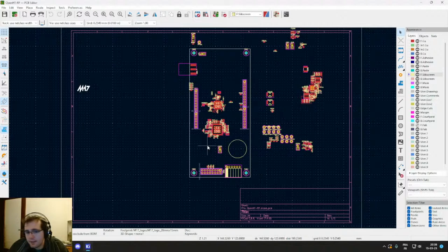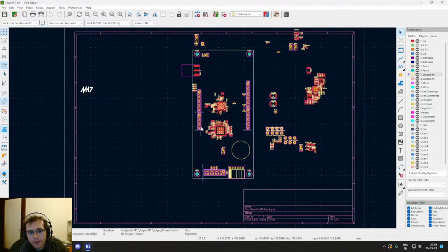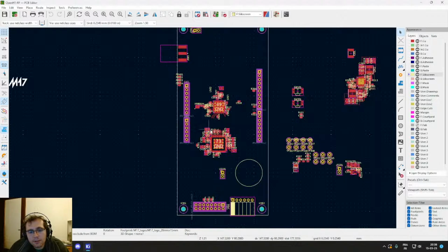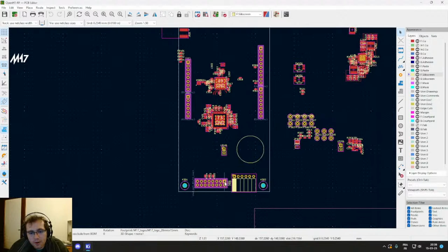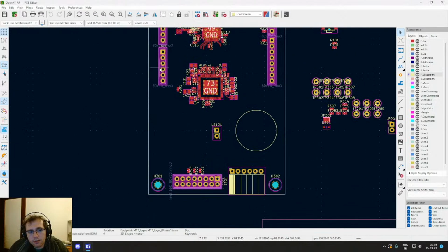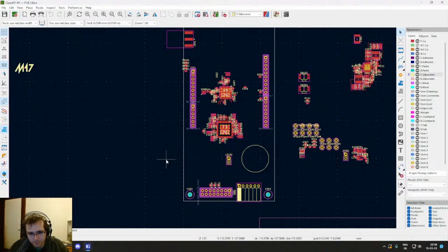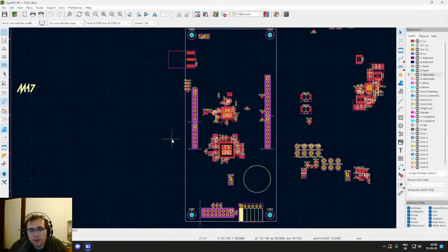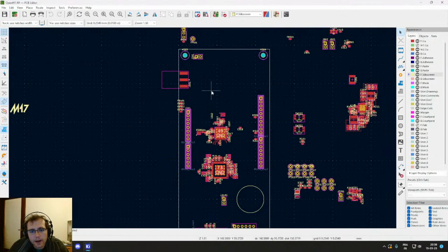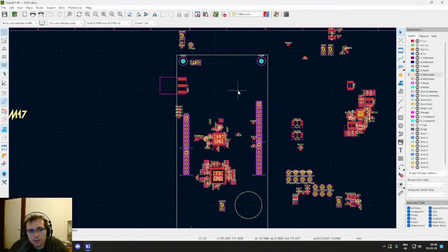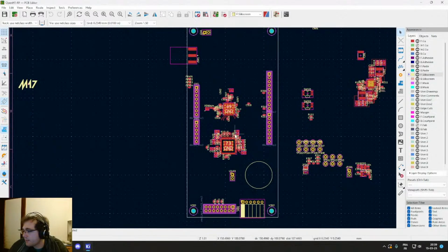So if you're interested, we basically had to open the Altium project file, so replace the connectors with connectors which do have holes and pins on it. The default doesn't. And then finally we were able to perform some measurements and place everything together. And then we did export everything in STEP files to check if there is no interference, which seems to be all right. So yeah, now the connectors are good and we can place the rest of the system.